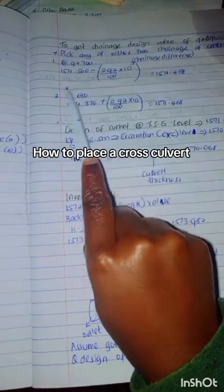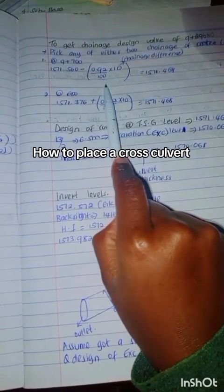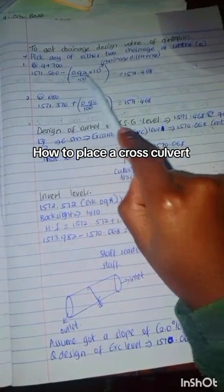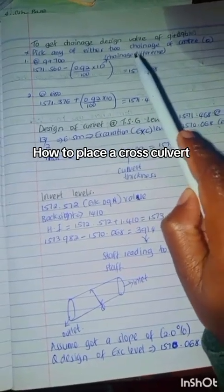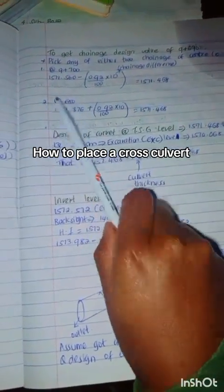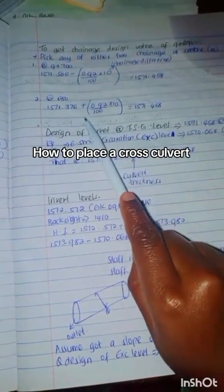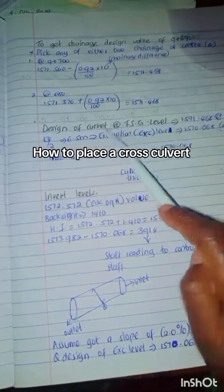You minus the percentage slope that you got, negative 0.92 over 100 multiplied by 10, that is the chainage difference between 690 and 700, and you get 1571.468. That is the design for 690. When you use 680 to get the chainage of 690, you change the sign from negative to plus, and you get the same answer.